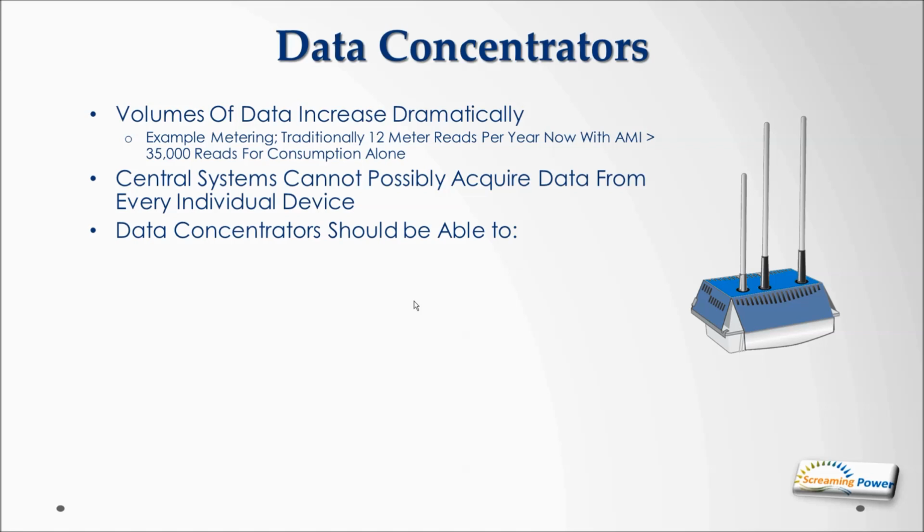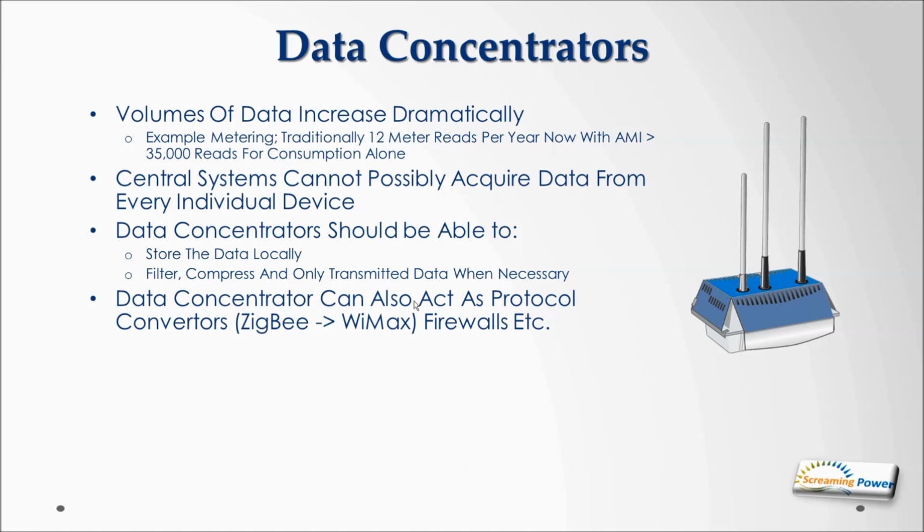The data concentrators should be able to store the data locally, of course acquire the data from any device connected to it, store it locally, filter, compress and only transmit data when necessary, so it doesn't move unnecessary data around the system. The data concentrators also need to act as protocol converters, for example ZigBee at the last mile to WiMAX into the backhaul, and it can also act as a firewall, etc.